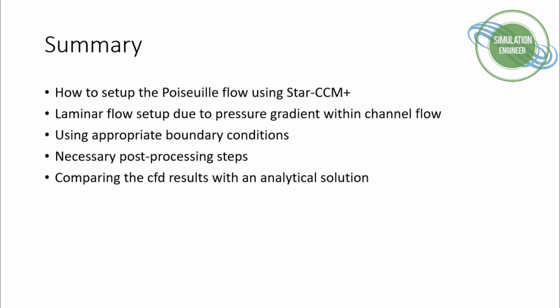We have fixed the two plates of this channel, the top and the bottom one, and we have imposed a steady state, fully developed laminar flow by imposing periodic boundary conditions. We have already done the necessary post-processing steps. And as mentioned earlier, I will repeat once again: comparing CFD results with an analytical solution gives us a really great comparison for such a case with almost 0% error. So with this, I conclude the simulation.